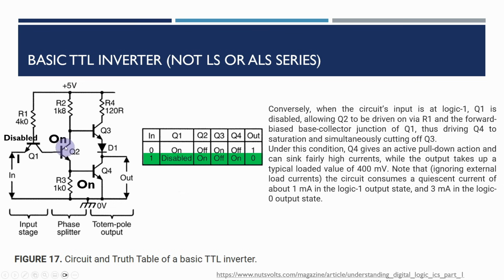Because this is turned on, then in fact this one will be turned on. So we'll have a current coming through here, down through here, and so this will enable this one to be on. And because this one is now turned off, because the input here is connected to ground through here, this one turns off. And so what we get now is 0 volts, but we won't get exactly 0 volts coming out here. It will be somewhere around 0.4 volts or so.